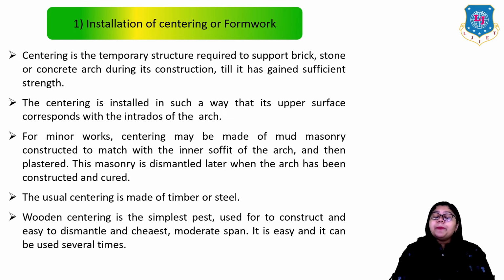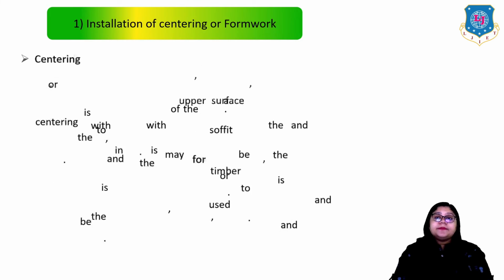Wooden centering is the simplest, or we can say the easiest one, which is used for construction and is easy to dismantle. It is the cheapest, and is good for moderate spans. It is easy and it can be used several times.